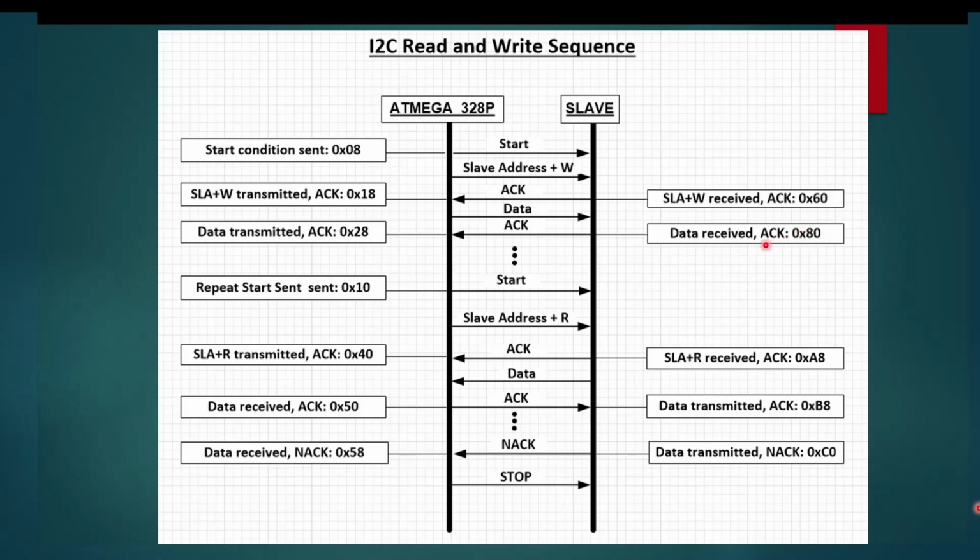So it's going to continue doing this until it gets its own address plus write command, which is going to be when it gets the status code A8. At that point, it's going to start transmitting data.